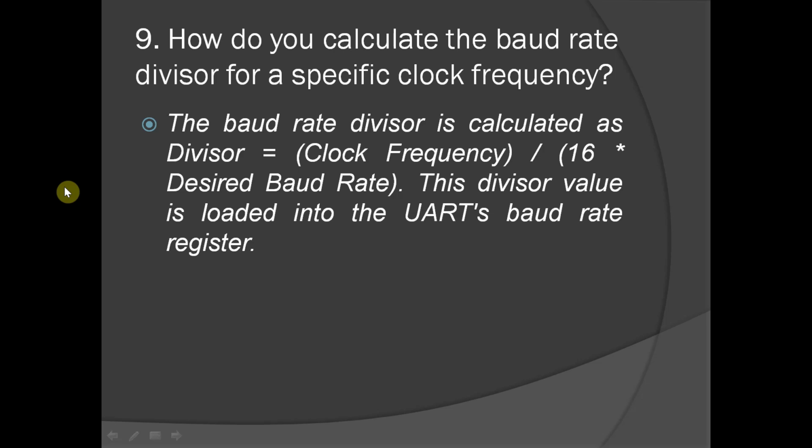This is the case in every protocol, where there is data mismatch. Actually, in other protocols there will be handshaking signals, but in UART you don't have any handshaking signals. Like acknowledgement, not acknowledgement in I2C, right? In the case of the AXI protocol, you have ready signal, valid signal, all these signals. They are used to indicate when the data is coming. Then the receiver will know when the data is coming and it will take the data like that. There will be handshaking signals, but in UART you don't have any.